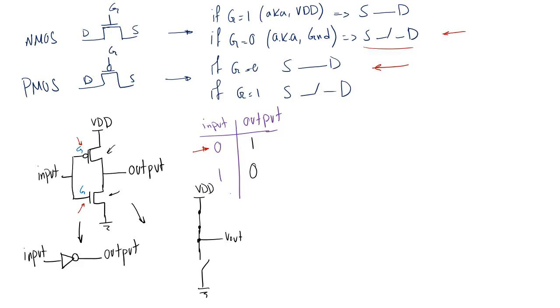But one thing that you're going to see that is common among all of these circuits is that they always have two sections. There's always a pull-up network and there's always a pull-down network. What do I mean by that? I mean that there's always a VDD up here, some circuitry, and some other circuitry, and basically ground.